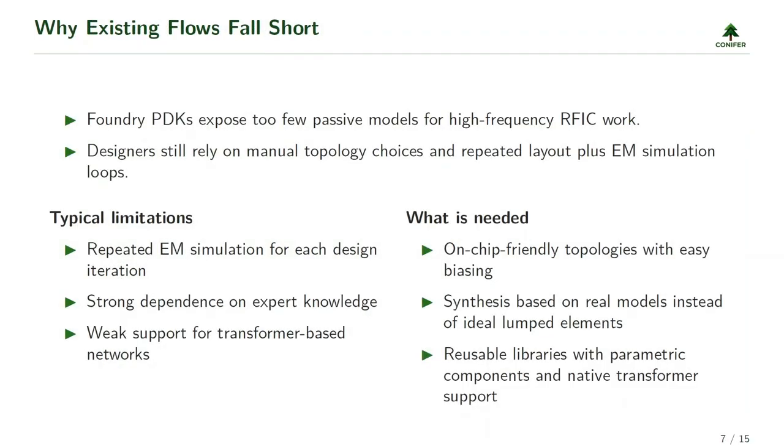The existing design flows for matching network design have significant shortcomings. One of the key issues is that generally foundry PDKs contain only very few passive component models for working with high-frequency RFICs. Another key issue is that designers still rely on manual topology choices and repeated layout plus electromagnetic simulation loops. This can lead to a large number of design iterations.